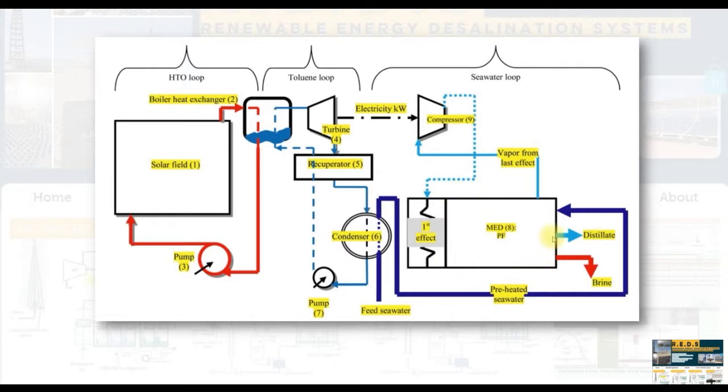For the MED, this is our MED unit. There is no end condenser. We are going to eliminate the feed heaters or brine feed heaters. The feed seawater is going to gain some of the regeneration energy, or some of the recovery energy, from the condenser unit, in order to condense the turbine working fluid, and gain some heat before going to the MED process. Okay.